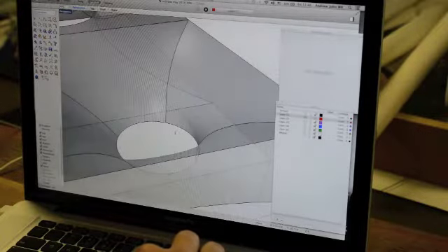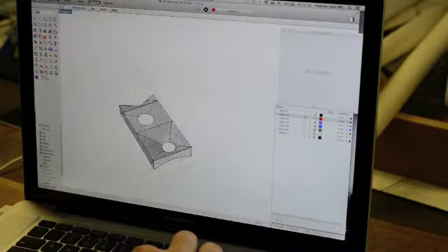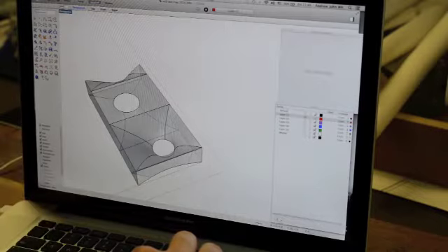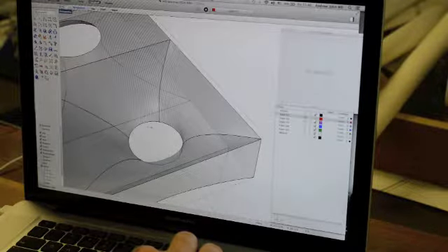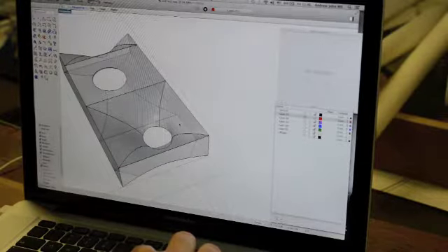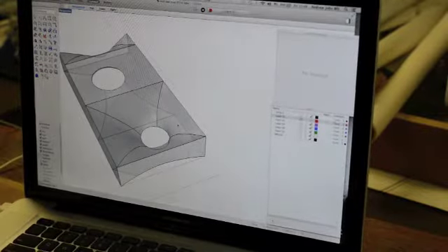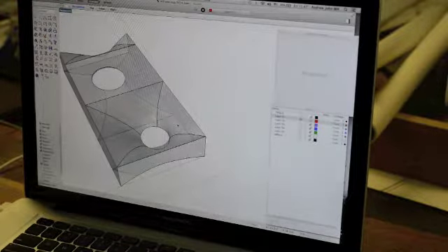So in Rhino, you need to duplicate borders. We're going to have to bring in curves in addition to the actual surface that we're milling. I'll set that up and then we'll save it and head over to MasterCAM.